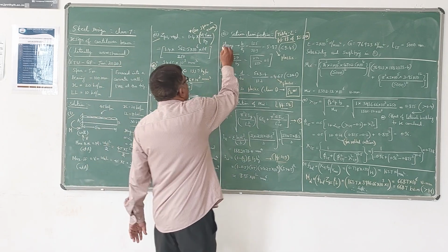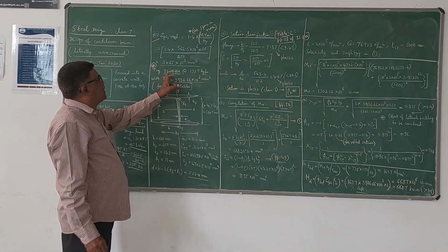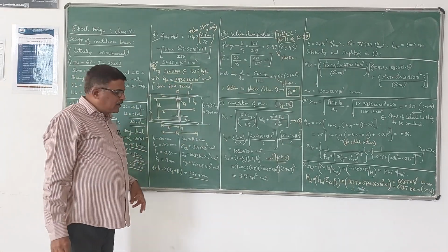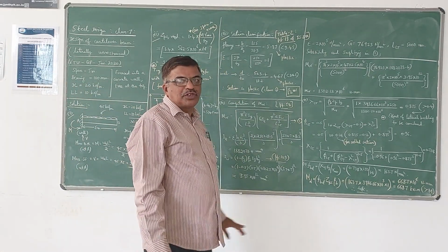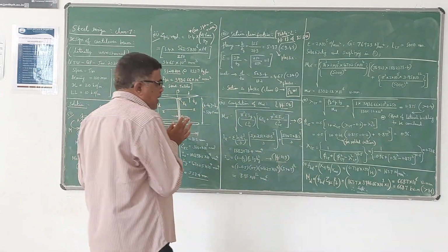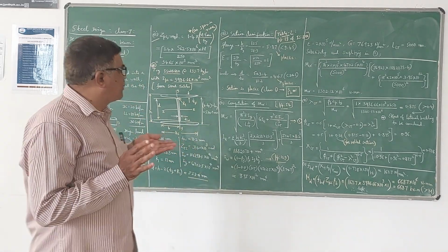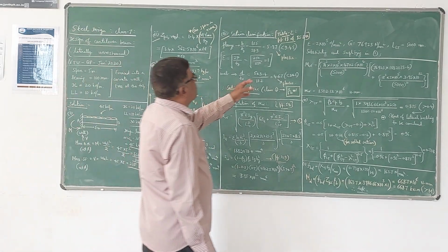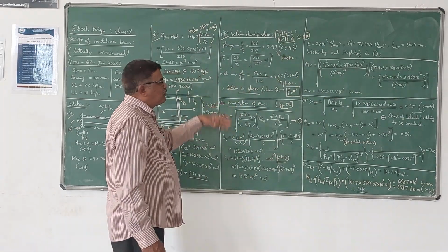Now, the third step, after choosing this wide beam, the ISWB section, the Indian Standard Wide Beam, is the name. We have to check the section classification because as far as possible we try to keep the section plastic or compact. So we have to check according to Table 2, page 18 of IS 800. We have to check both the flange and the web.